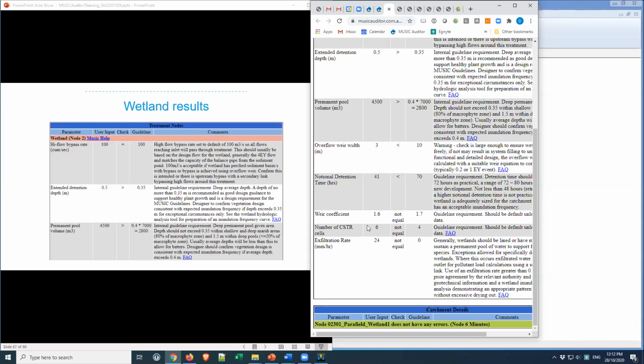And the other parameters we've got here, this is something that's not uncommon. These are basically parameters we expect to be the default that have been changed. So, weir coefficient, you haven't even bothered to change the weir width. Why would you change the coefficient? That's probably a typo or just a random change the consultant's made. We do see these from time to time, so this just picks up all those default parameters and flags them. When would you change that? When you've actually got a weir design, you're not using a standard weir, and the particular weir you are using needs a different coefficient, and then that would be a justified change in that situation.